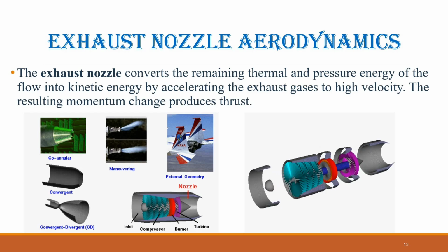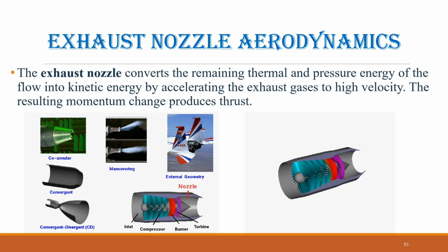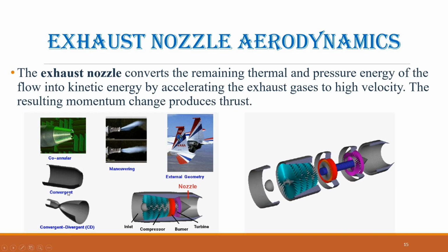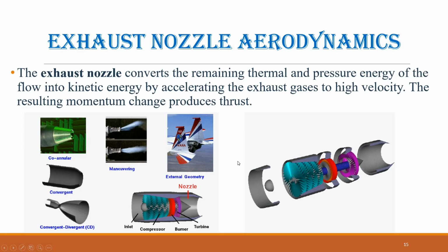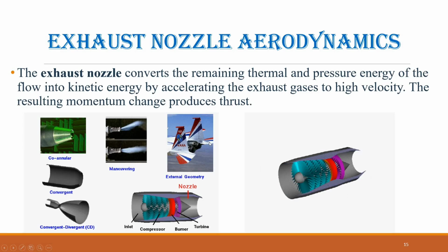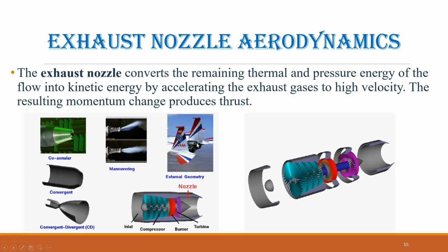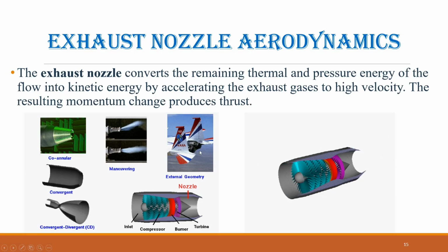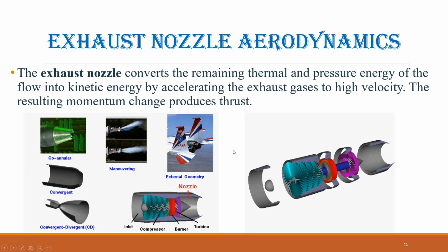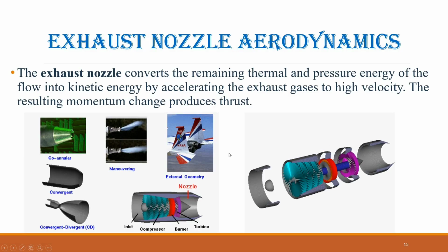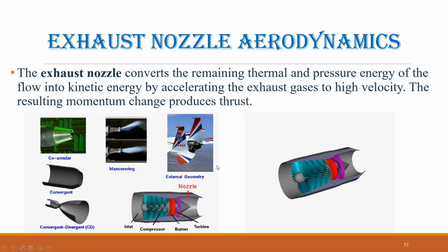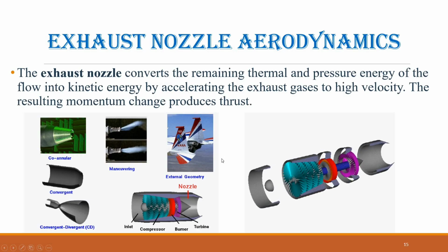In commercial aircraft, exhaust nozzles are typically fixed geometry and optimized for cruise efficiency. In military aircraft, variable geometry nozzles are used to adapt to different flight conditions. The F-22 Raptor uses thrust vectoring nozzles that not only optimize expansion but also provide control forces for extreme maneuverability.